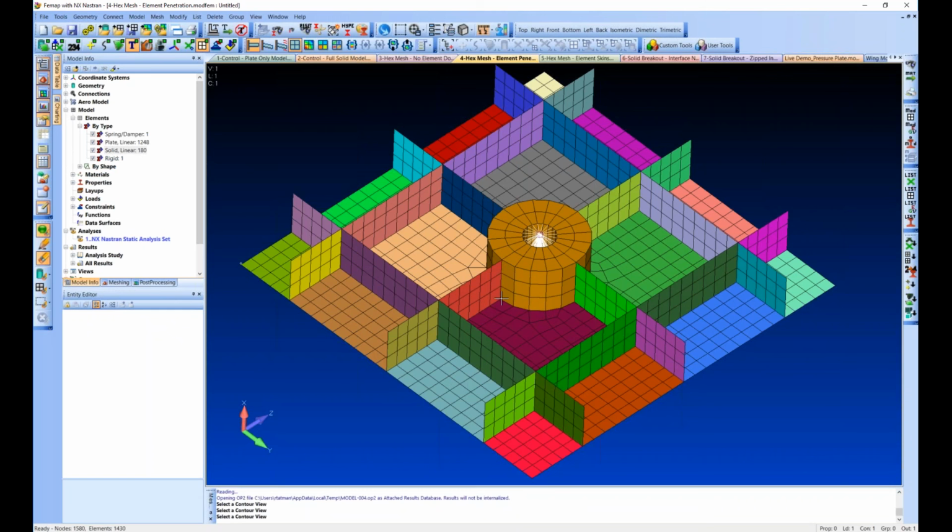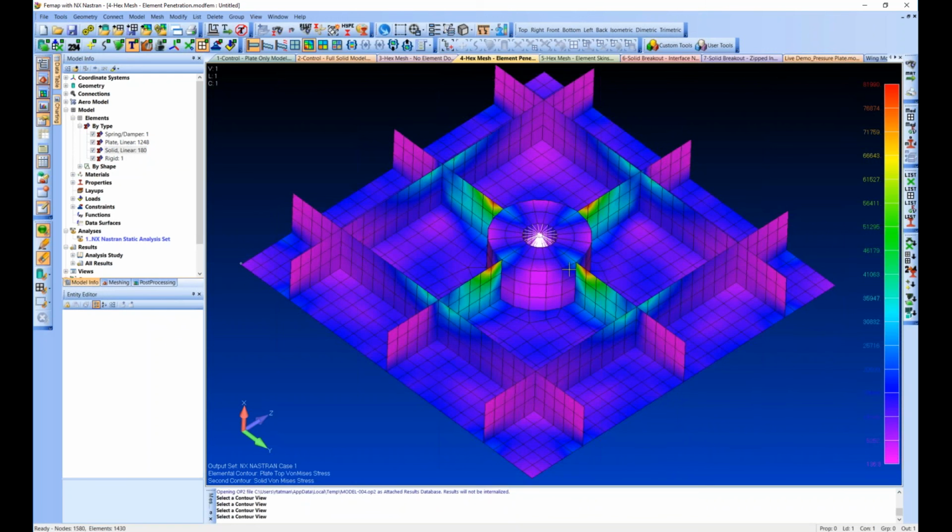Basically, you want to solve this hinge condition here. So there are some solutions to that. This is element penetration. So you've got your rib elements that are going into your solid. So all of your nodes are coincident, and you're just moving these rib elements into your solid. This will run, right? You're not going to get excessive pivot ratios because you've solved your moment problem at the hinge here, but you've added material. So you've added stiffness, you've added mass, you've added strength. So you'd expect to see a lower stress, which is what we find, 82 KSI. And it did push our stress concentration farther out.